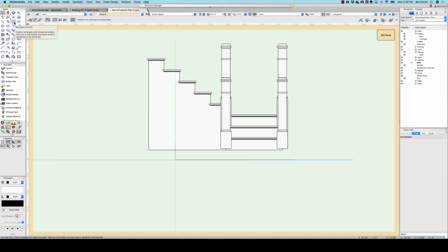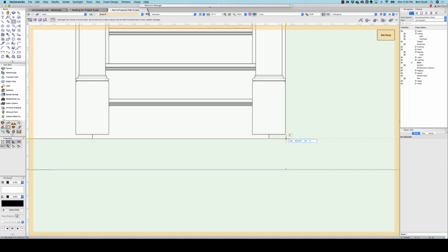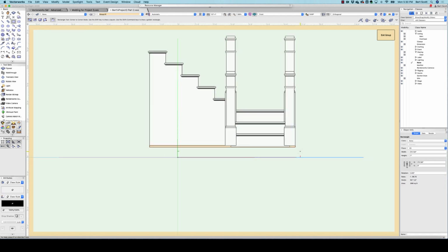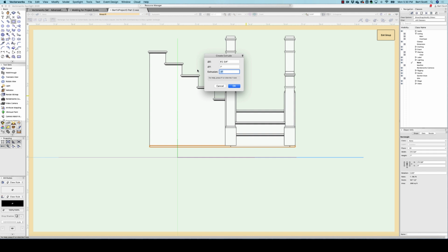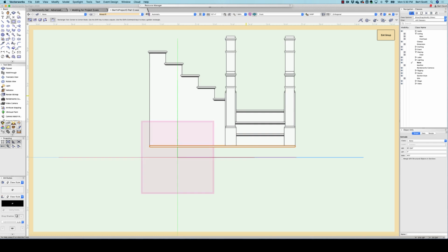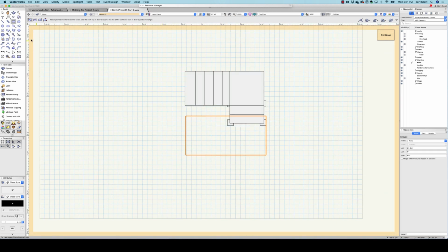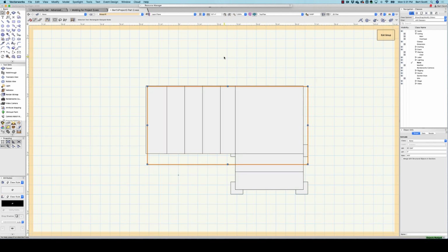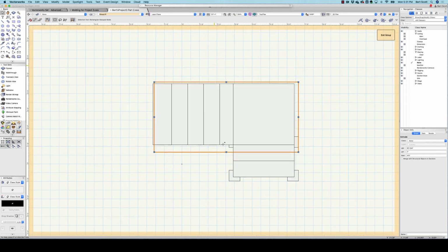So we're just going to subtract the bottom of the staircase. I'm going to draw a rectangle that's that high and extrude it 4 feet, I think. We'll try that. That should work. Then I'm going to go to top, and I need this to be under the entire original staircase, and 4 feet wasn't enough, but fortunately I can just stretch it.